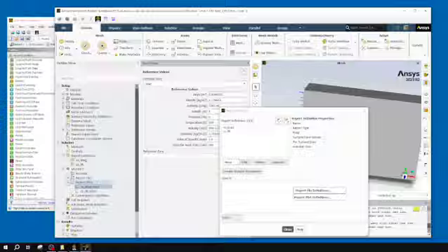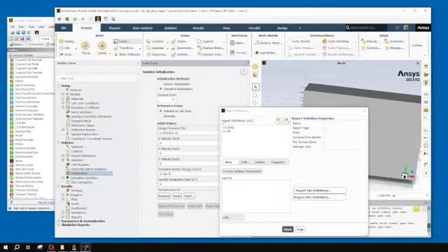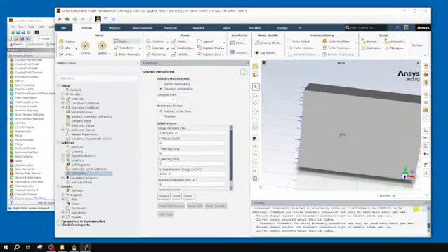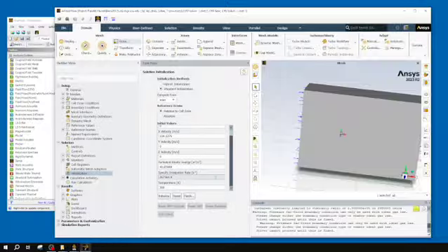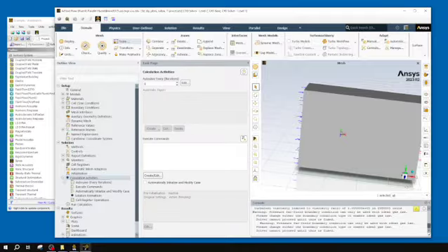I'm going to move on down to my initialize. Can close this out now as well. Usually the default is hybrid. I am going to move it over to a standard initialization, and once again go compute from my inlet. You can see it inputs my velocities, my turbulence, my dissipation rates, and my temperatures. So now every cell will start at that velocity. Just makes solving it a little quicker. There are no calculation activities that I need it to do, but I'm going to move down to run calculation, double click on that.